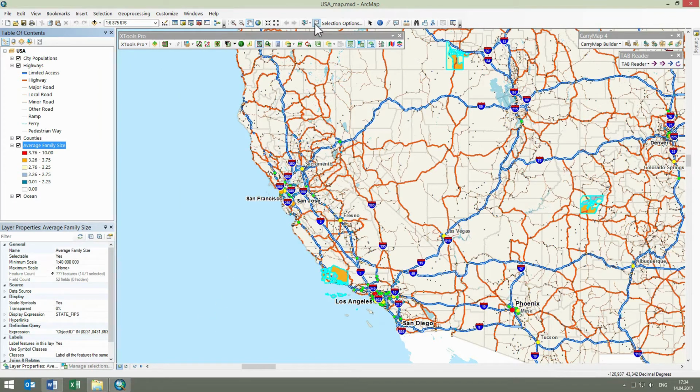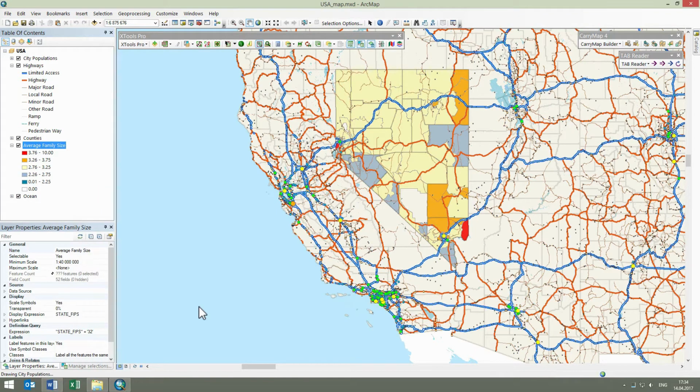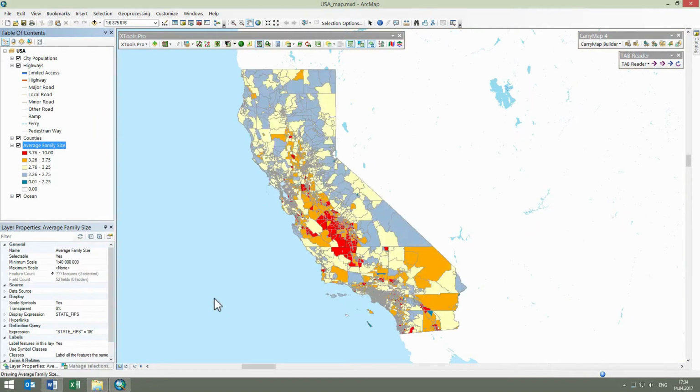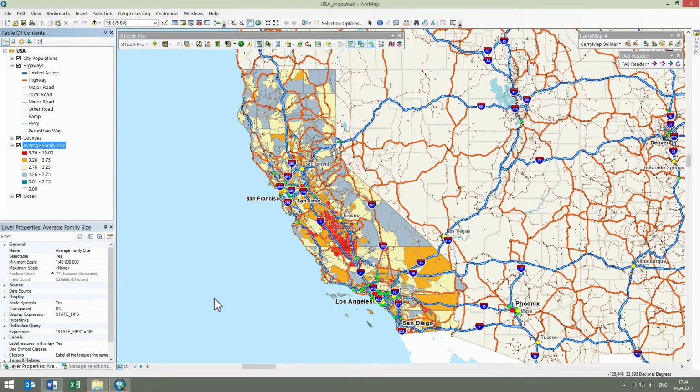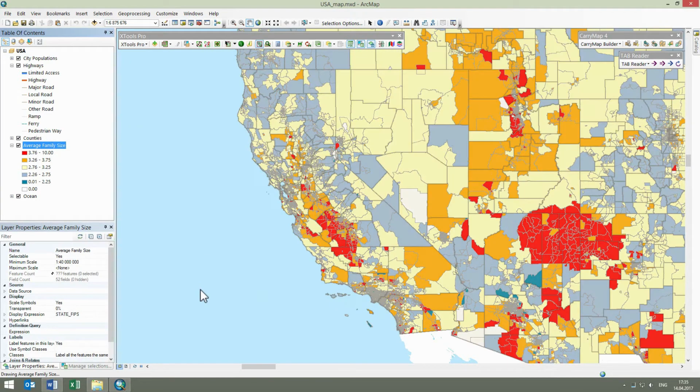Now, we clear selected features on the map to concentrate on the queries. Let's get back to the Layer context menu. Now all queries have meaningful names and we can easily see what features are behind the queries. We can enable the required query simply selecting it from the menu. Disabling all queries is also possible from the same menu, if we select the None menu item.